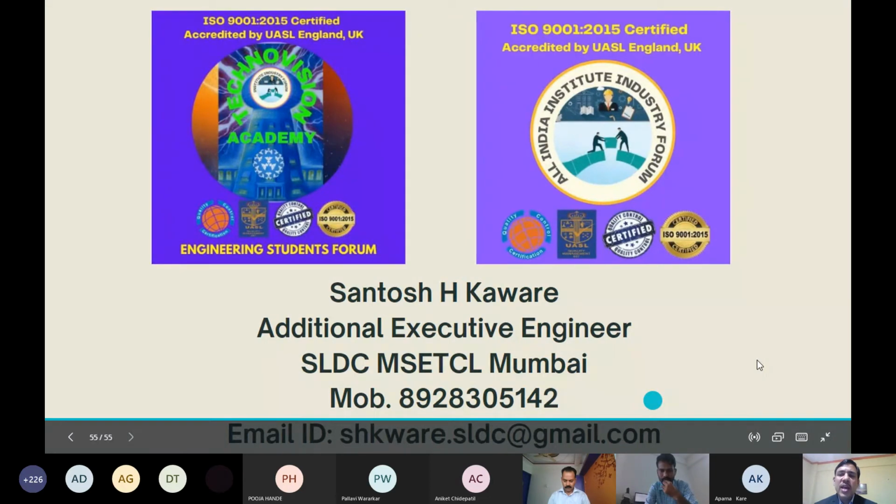We have a gang operating device. Gang operating means you operate all three phases at the same time. You open one switch, and all three phase connections get opened. So you perform the operation of that isolator at the same time, and all three phases get disconnected at once. That is gang operation. Any other queries?